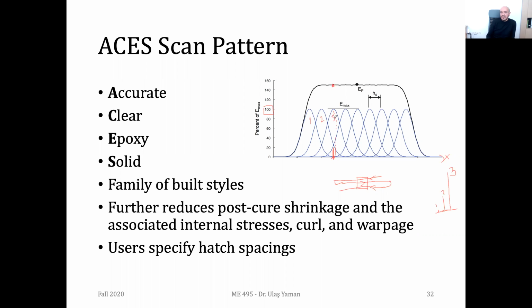But once you pass 3 times through the same point, you can go up to about 50% more, and it will be 150%, as you see here. So the summary is that by having such a special pattern, you can cure more difficult material with the same laser. But the problem is that you need to spend more time.